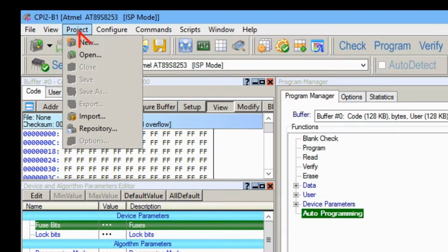The Project window allows you to create, store, and manage programming projects. A project is a fundamental concept for the ChipProg ISP2 device programmers. Instead of using single steps, such as choosing the device to be programmed, browsing for the file to be written into the device, and setting other properties, it's much more convenient to specify all these options in a single project, store it as one project file, and then open this project file by one mouse click, or by calling it in the command line, or as a DLL parameter.